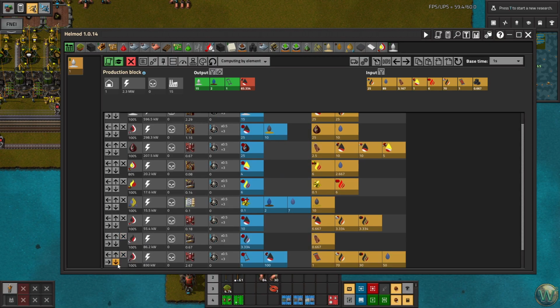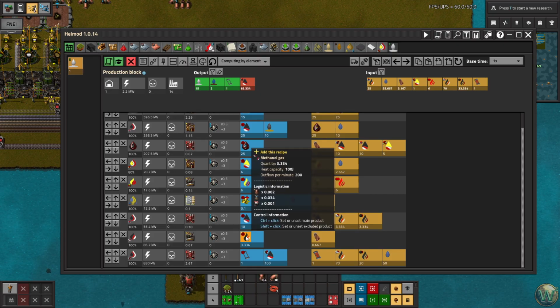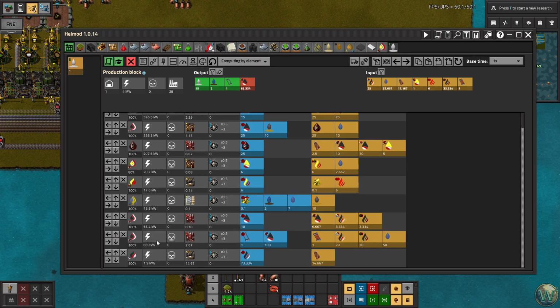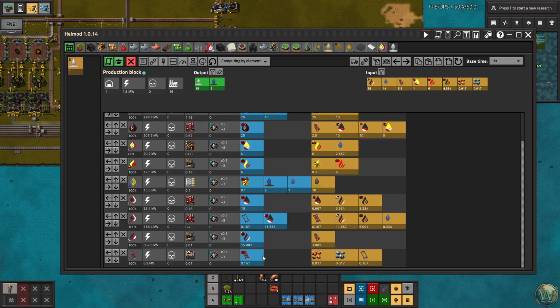I'm going to delete these last 2 from here just because we're going to add them back in a little bit. I don't want to do it right now. We're going to add them back in with this. So methanol and carbon monoxide. Oh, I need this methanol to be down here, down 1, 2. Okay, increase that supply there. Acetone and carbon monoxide. Yep, okay. So we can go ahead and do the catalyst thing, just so we have it on the screen here.